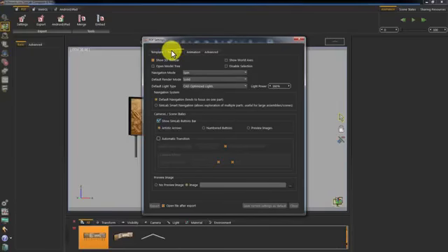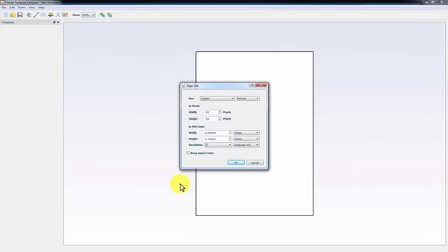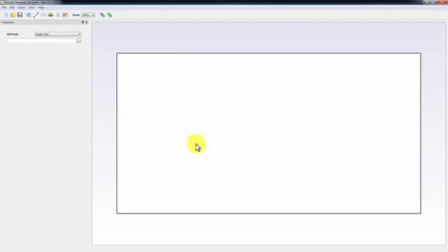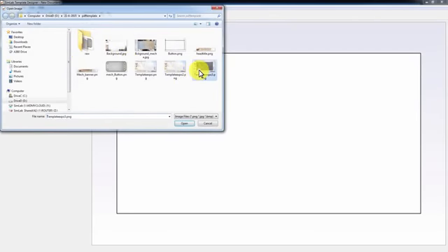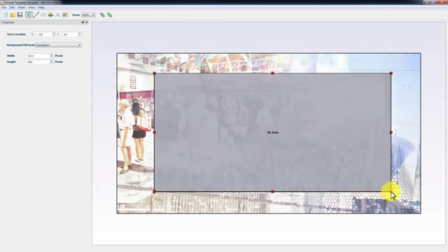Go to the Template tab and click on New. Change it to Landscape and set the resolution to 1300 by 685, which is suitable for the image to be used for the background. Change the fill mode for the background to image and select an image. Click on the 3D area icon to place a 3D area in your PDF file. Use the red draggers to adjust the size and shape of the 3D area.